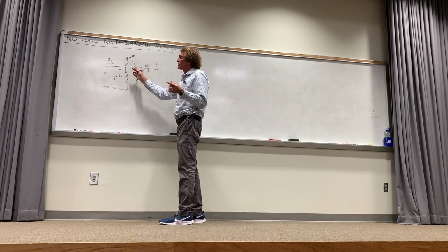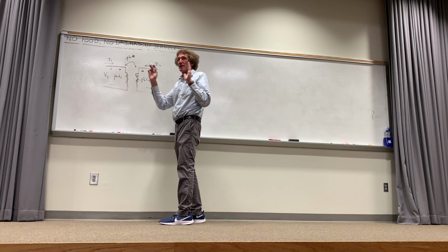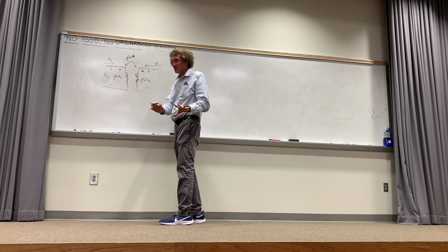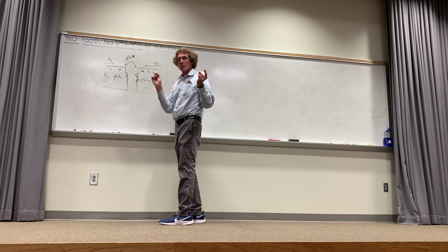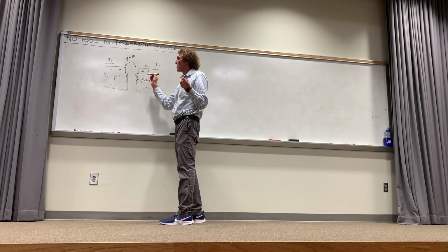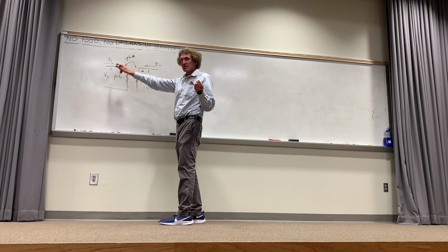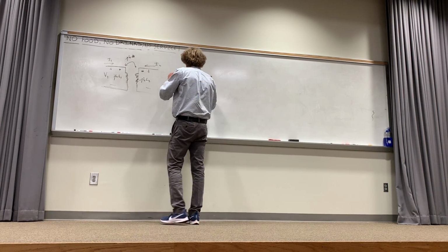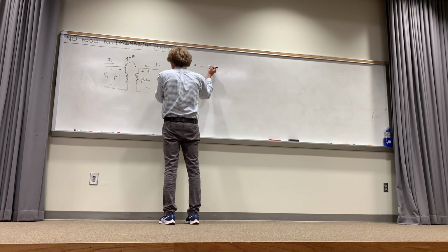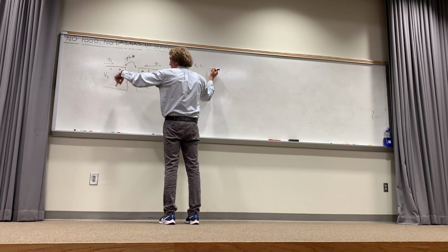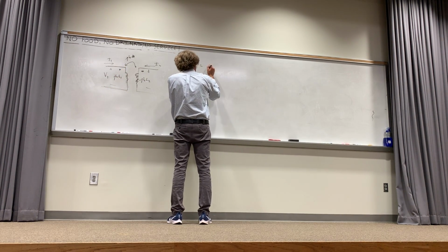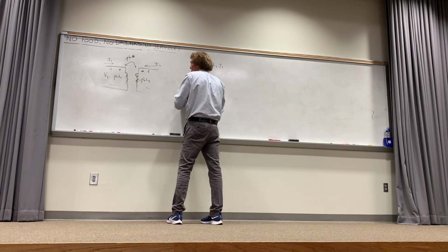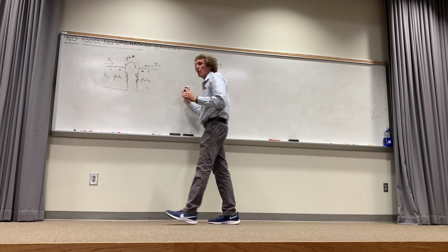Remember, current enters the dotted terminal by the convention we're going to use. Just keep this in mind and you will not go wrong. You put your currents into the dotted terminal. If you're on the primary side, it's I1; secondary side, I2. Now the voltage V1 here is just like the voltage would be if that was only an inductor. It would be J omega L1 times I1. That's the voltage due to just the impedance of that coil.